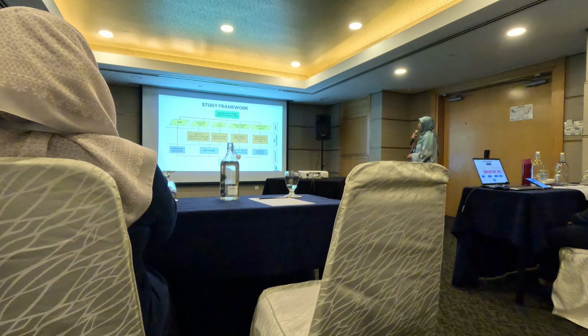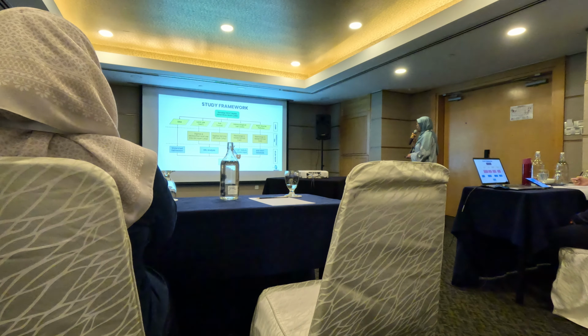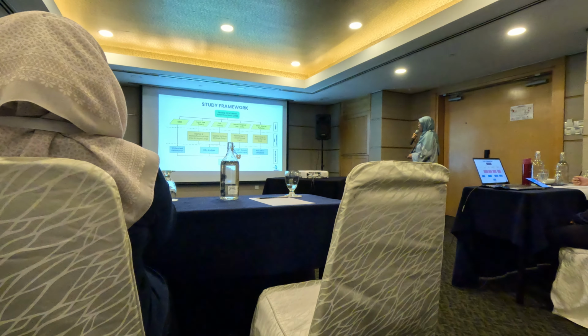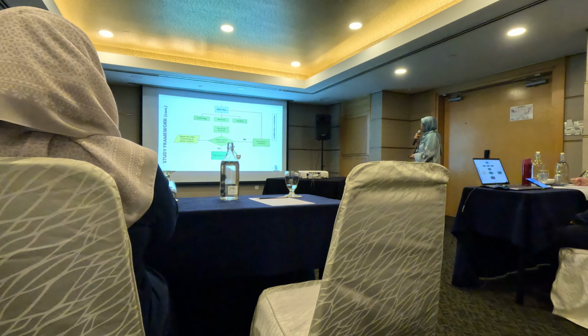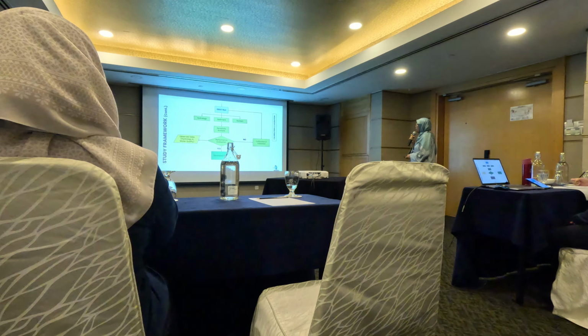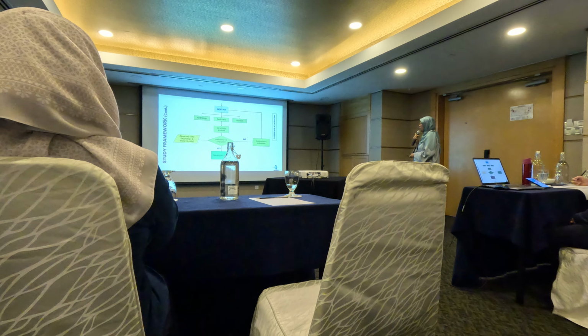After land cover and the DEM, I need to do watershed delineation, and from the land use and soil I need to do HRU analysis and input the weather data. Then I can run the SWAT. After running the SWAT, I need to make calibration and validation. Firstly, I need to calibrate the streamflow. After that, sediment and nutrient.